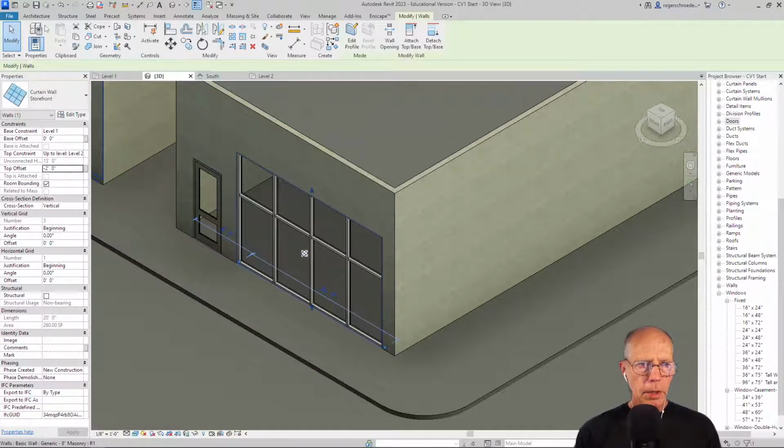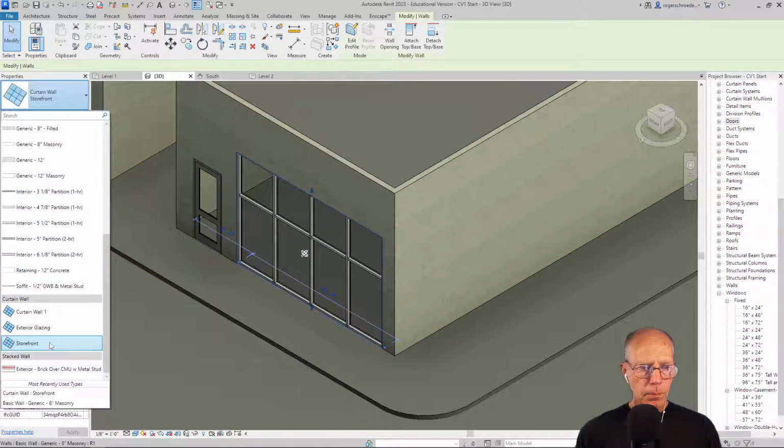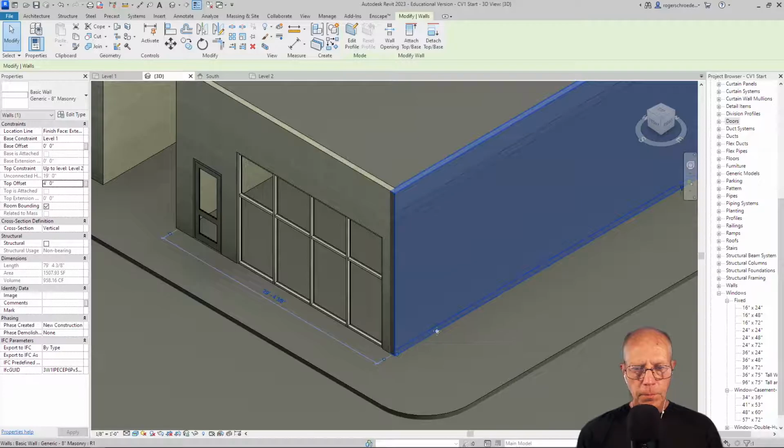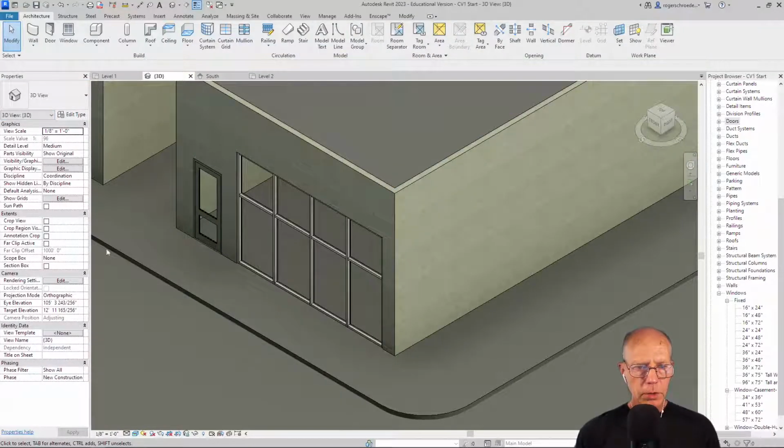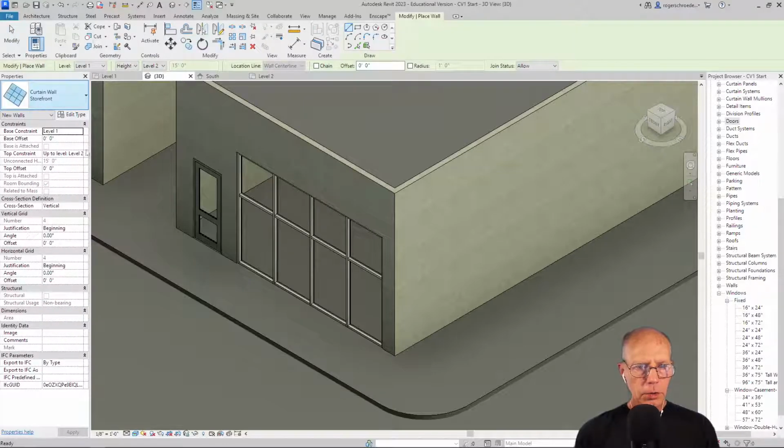And we're going to go ahead now and construct some more of that. So I'm going to grab that tool again. I'll come over on this side. Oops, I've gotten into a strange mode here. Let me grab the wall tool again. Architecture, a storefront, and now on my drawing tool, we'll start 2 feet. Well, actually, go even closer, 1'6".